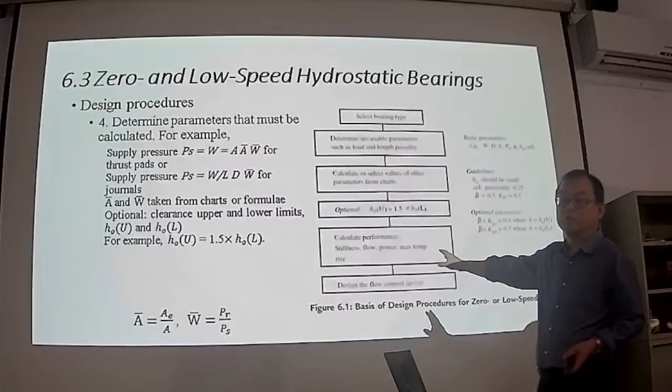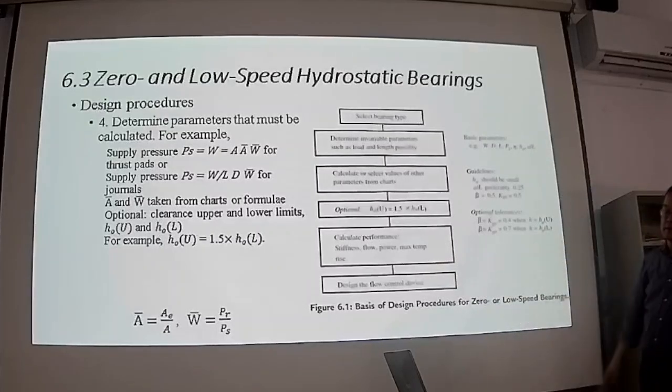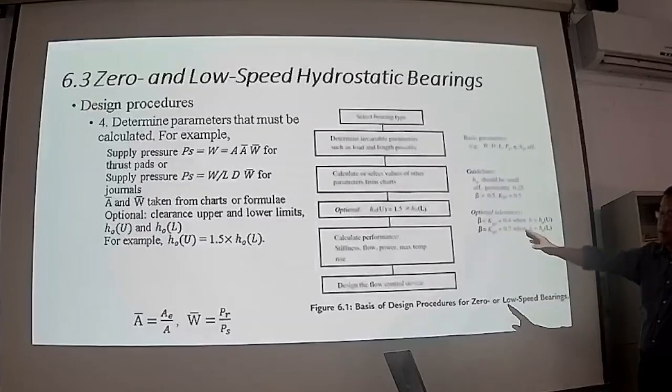You need to check the final film thickness very carefully because it may change all your bearing performance. Okay. So according to the final film thickness, after the assembly, you will make some adjustment for your pressure ratio.